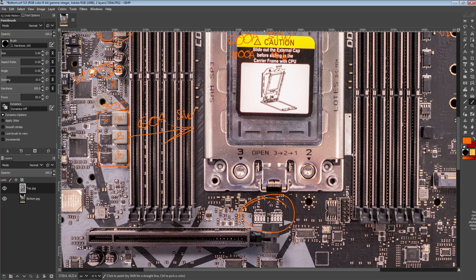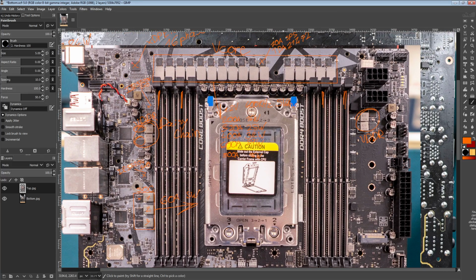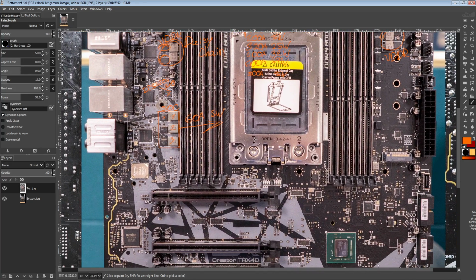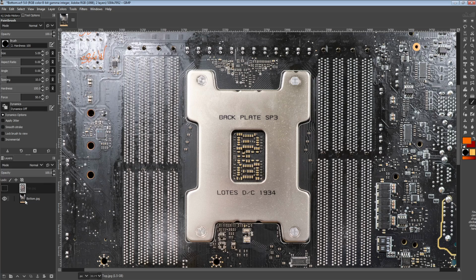Motherboards where you have to go into the manual to figure out which DIMM slot is what are kind of annoying. Though with 99.9% of modern motherboards, you're going to be going outer DIMM slot first, just because of how the memory traces are configured. So, yeah. Anyway, I think that's everything about the power delivery.